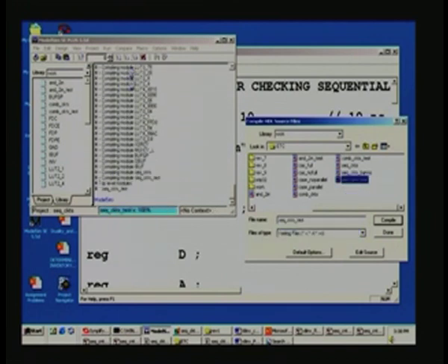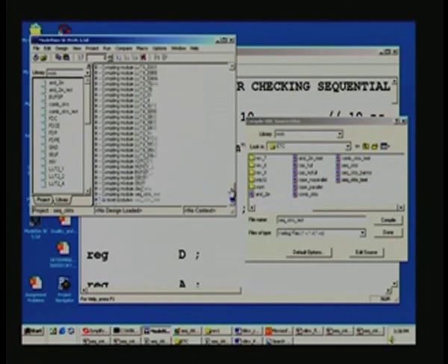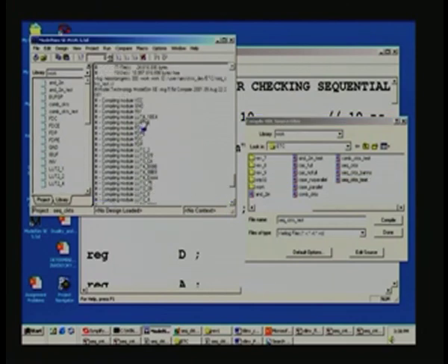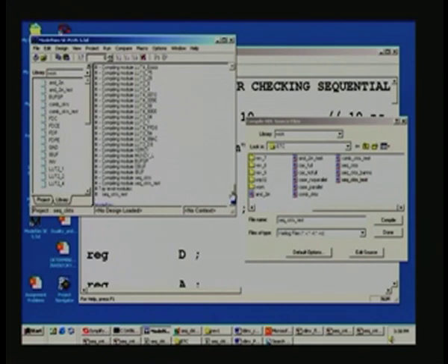When you double click here, you see it gave a big list, and I will read it for you. You are already familiar with the synthesis, having created LUT4, LUT2 and FDC, FDP, then once again LUT, D flip flops for FDP, and so many LUTs, then mux, buffer, input buffer, output buffer.